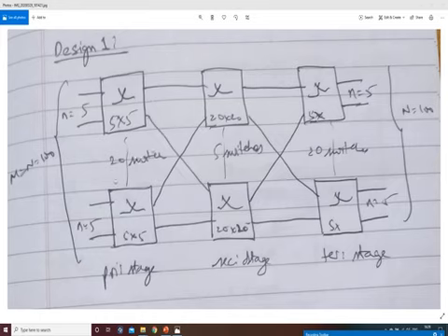Now since there are 20 primary switches, it indicates that in the secondary switches, one link comes from the first primary switch, the second link from the second primary switch, the third link from the third primary switch, and so on up to the 20th link from the 20th primary switch. So which indicates that there are 20 incoming inlets to the switch in the secondary stage.